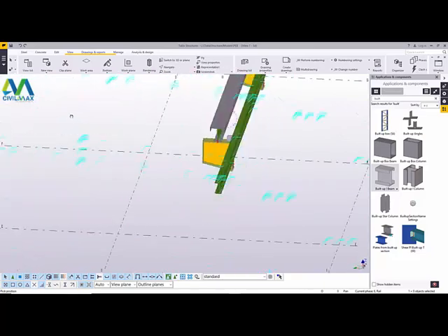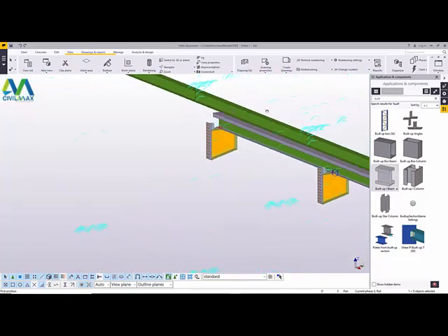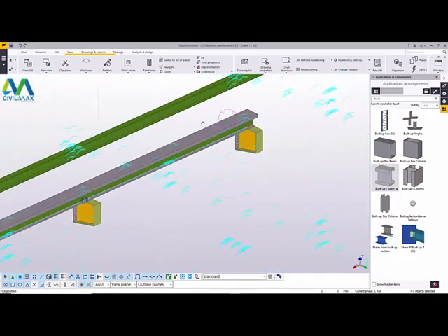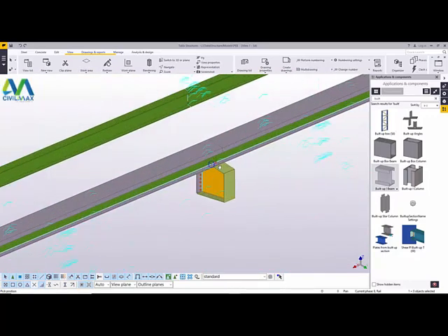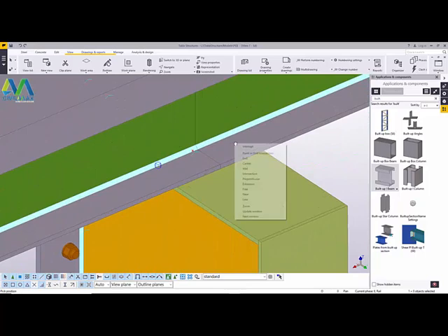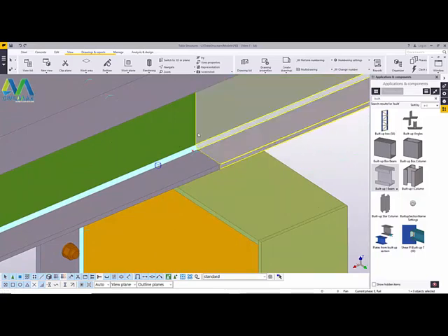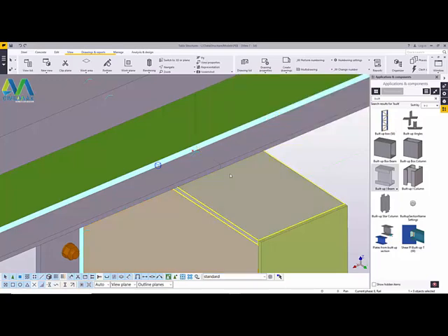Now I'll turn this round and check whether everything is in place, and prior to bringing back other parts, I want to start clamping my girder, and I want to start from this spot. To do that, I'll first of all mark the position where I want to place my clamps, where I want to clamp my girder from.